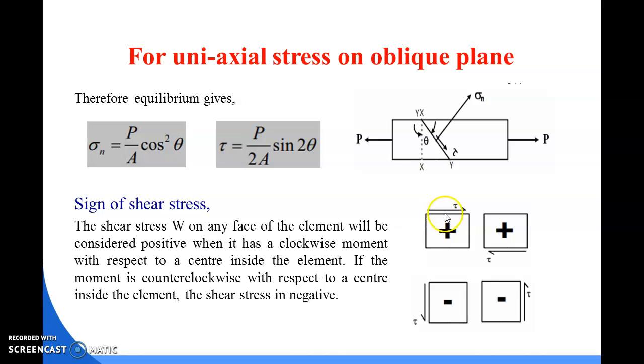say that here it is the object and on the upper side here one shear stress is there, and at the lower side here another shear stress is there, and you can see that all the shear stresses are opposite to each other. That means it is directed to the right side and the lower one is directed towards the left side. That means here the shear stress gives a clockwise movement. That means if we consider this shear stress, then it gives a moment of this type.